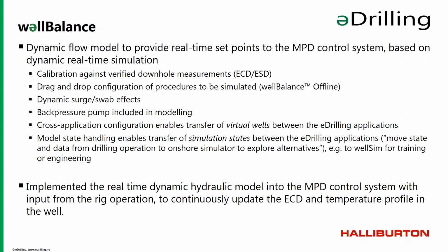So what we have been doing here is that we have implemented the real-time dynamic hydraulic model into the MPD control system. In this case, it's the Halliburton GeoBalance system. And then we use the input from the rig operations to continuously update ECD and temperature profile in the well. And then we continuously update the choke pressure set point all the time, so the control system can control the choke to achieve the proper pressure on the choke. That will also give you the proper pressure in the downhole where you want it. Okay?